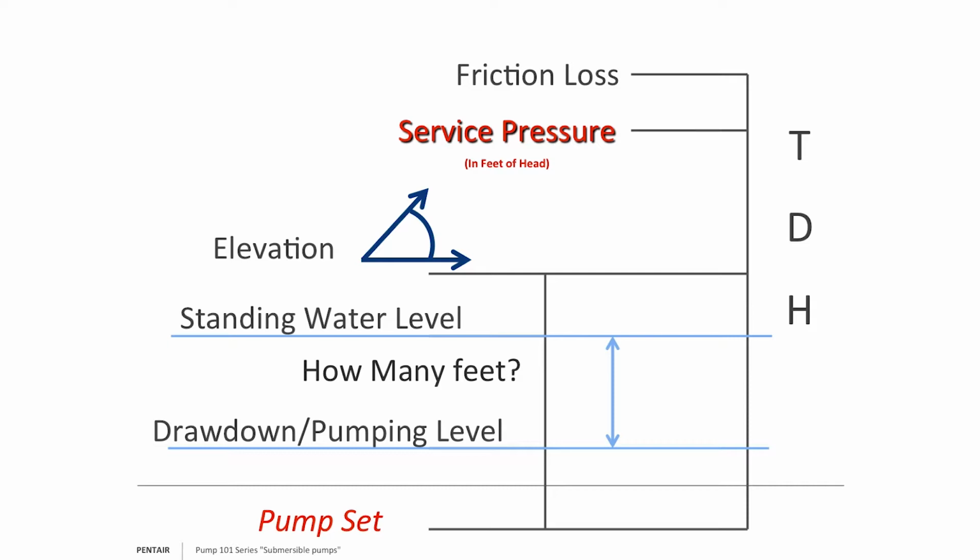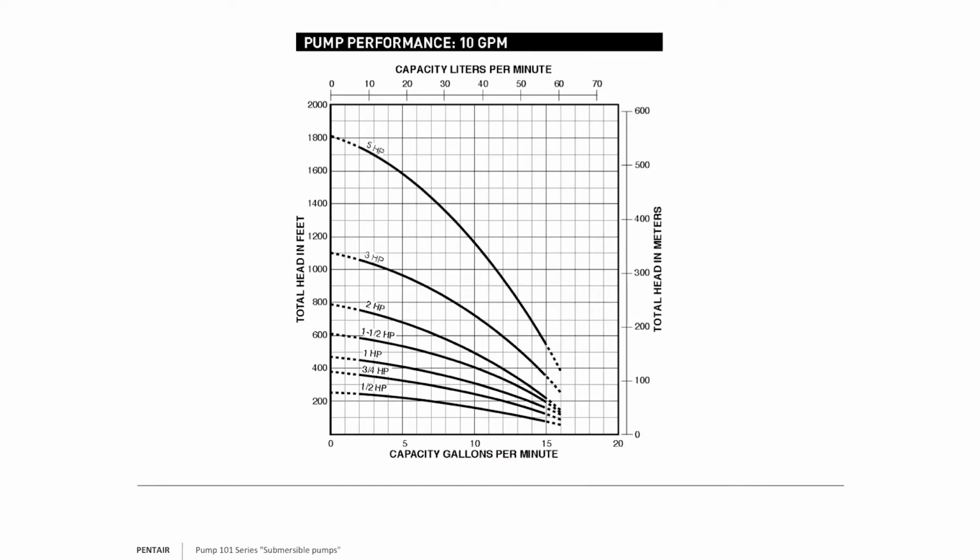It took us a while to get here, but I wanted to make sure we made this journey complete. A pump chart is based upon gallons per minute and feet of head. That's how we test it. That's how you size it. So looking at this chart, one of the things I often get questioned is, when I look at this chart, the dead center point is the best efficiency point. That's just the golden rule. And I've heard that quite a bit out on the road this past year. And the answer is no.